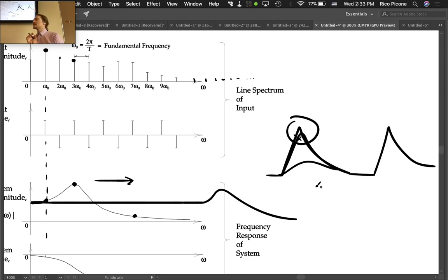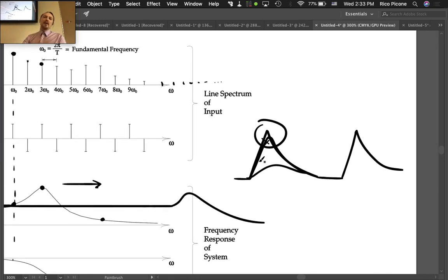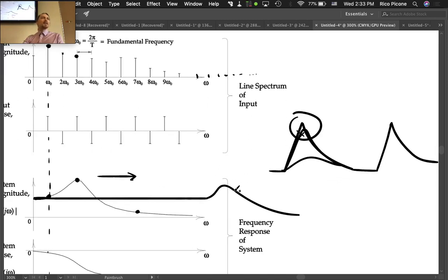But what you can do is you can say, okay, let's just reason our way to, like, approximately, what do we think this profile is going to look like? Like, what do you think the max is going to be? I know how long that tire is going to be in contact with it when it rolls over. So let's say that it peaks here and it has this sort of triangle shape to it. If that's what the shape was, what would I need for my measurement system, frequency response? Then try it, see if it seems like you're getting a good readout.